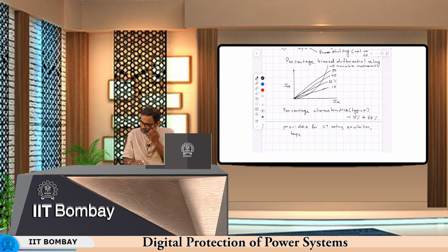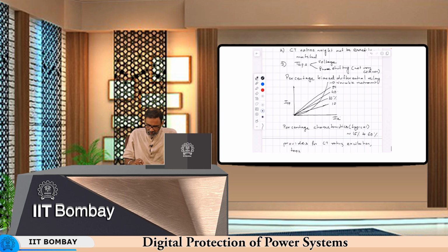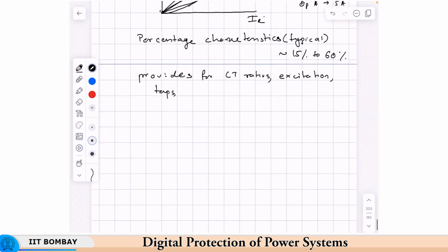So what does this imply? Say, what does a 50% tap imply? Just as an example, 50% tap implies that for an external through fault, meaning not in the equipment, current of 10 amps, the operating current will be 5 amps. That is what a 50% characteristic implies.